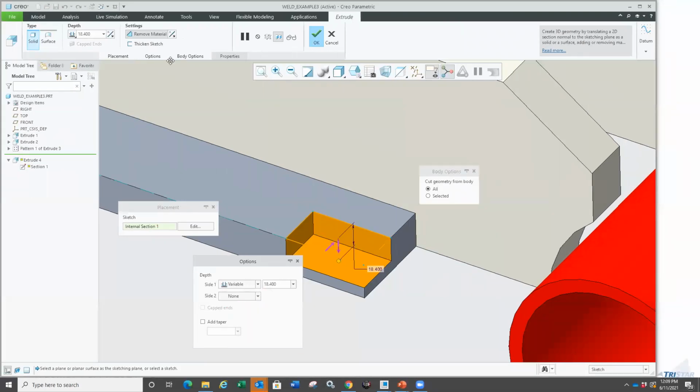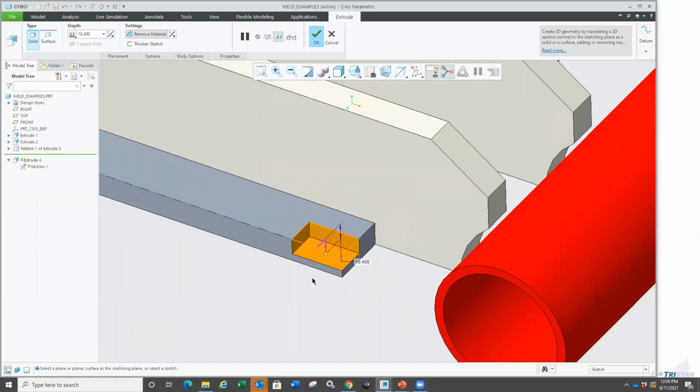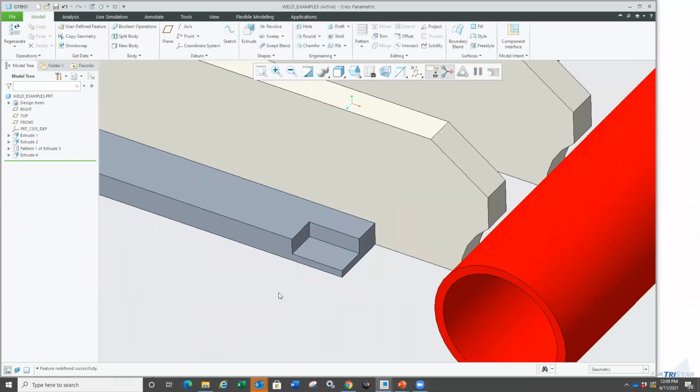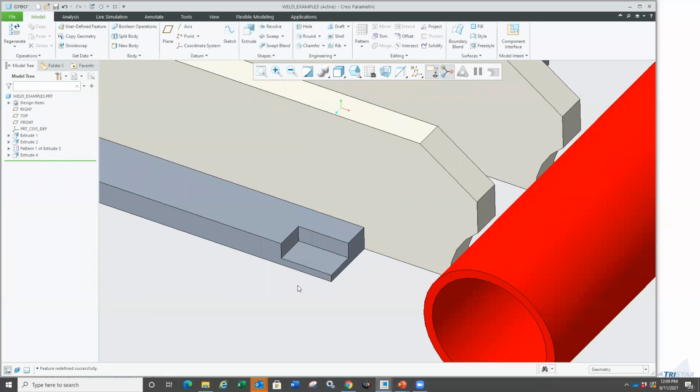So you can either dock it, or you could just minimize it. You can just click on this little guy right there, and it minimizes that, right? So mainly, it may not be that helpful for basic features. Maybe for more complex geometry, when you do a variable section sweep, or when you do welds, or maybe even in sheet metal design, where you'd like to update the relief type. You want to change the shape or the profile. So that's when it'll be nice to have those tabs automatically open, right?